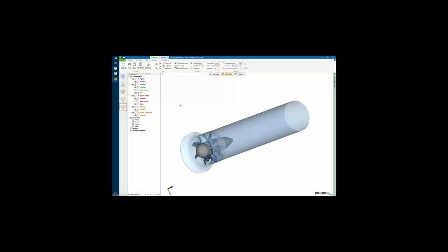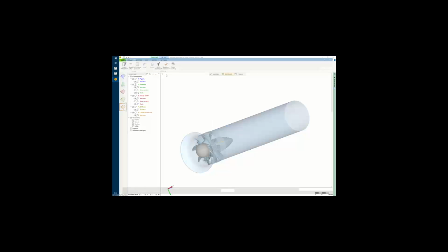All of our turbomachinery components are fully defined by geometry parameters. So in the next step, we are going to configure our parameters and transfer them into the parameter set inside of Ansys Workbench. So I'm just going to open the Ansys Workbench menu. And as you can see, the available parameters of the project are displayed in a tree structure according to their components and the design steps. And each parameter can be activated or deactivated individually.